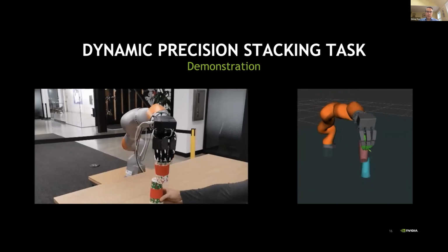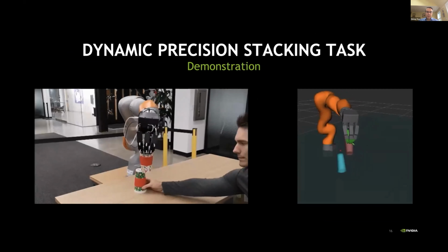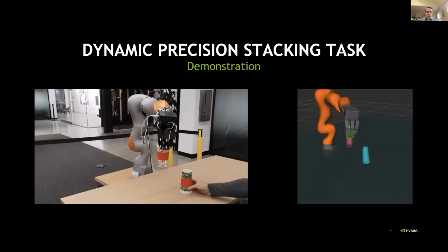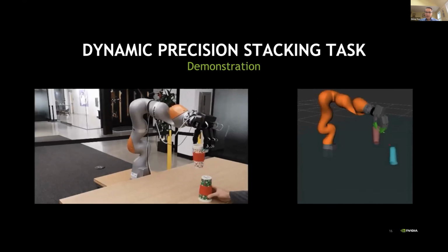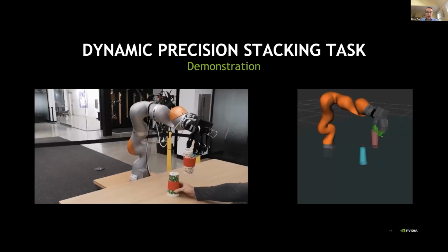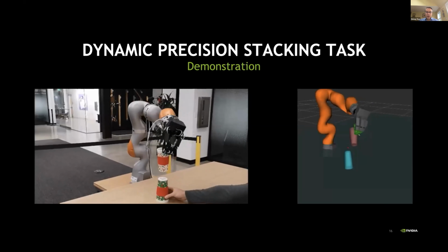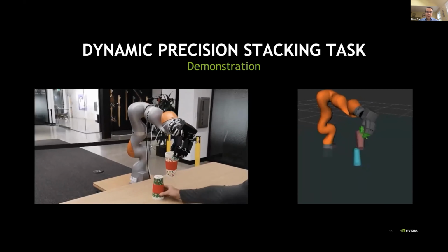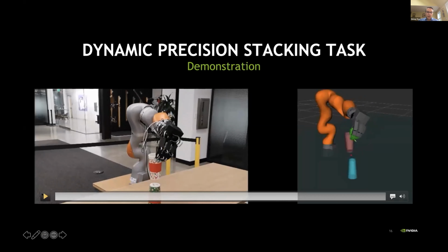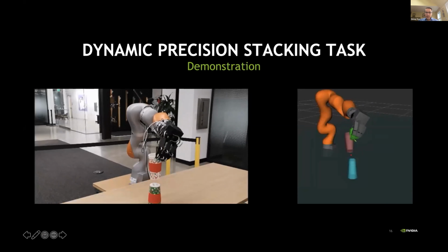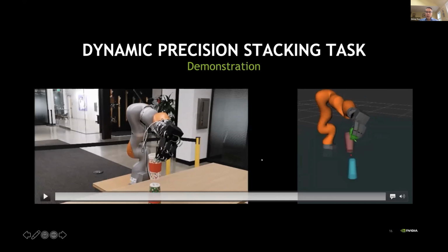Okay, and the robot now tries to put it back onto the other cup. But Carl is not nice and just keeps on teasing the robot, and we keep track of all of this in real time. And in this case, in this video, as you can see, actually the goal point is not defined with respect to the fingertips of the robot, but the goal point for the motion controller is actually defined with respect to the cup where it wants to place it.